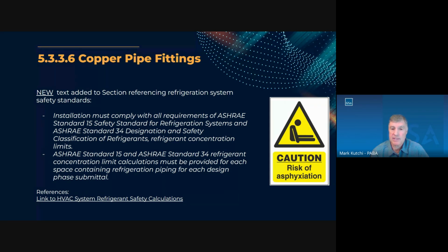The point here is that refrigerant, if it leaks into the room, is heavier than air. So it fills up a room like water fills up a bathtub. If the refrigerant isn't allowed to leak out to another room, then it could rise above a person's head level and suffocate someone. ASHRAE has had these refrigeration ventilation requirements for quite some time. What's changed is that the standard has been updated, and I'll get to that in the next few slides.